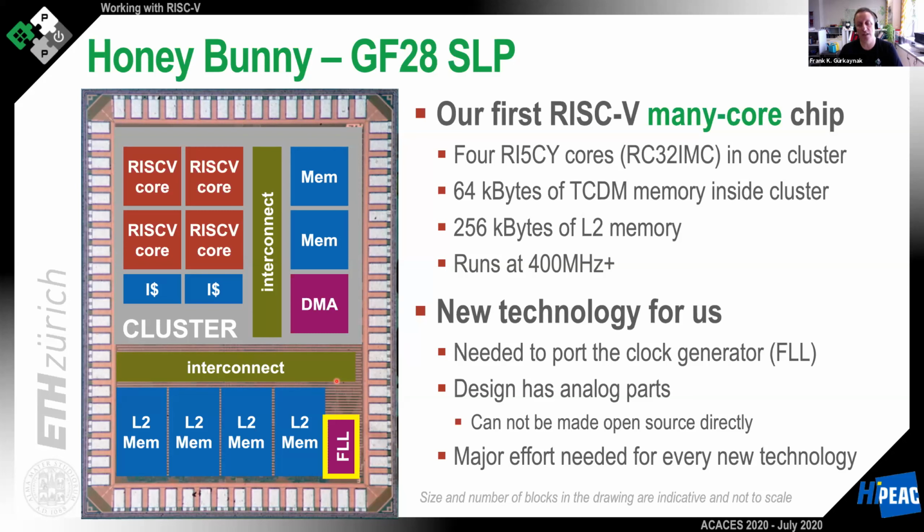And every time we have a new technology, some major effort is needed so that you adopt these things. And if you are adding more things, if you are adding ADCs, serial IOs, fast LVDS pads, etc., you also need to port these things. And you pretty soon realize where the limits are. In our case, the memory controllers for modern technologies like DDR or HBM are actually the major pieces missing for us to go forward and make even larger and more capable chips.